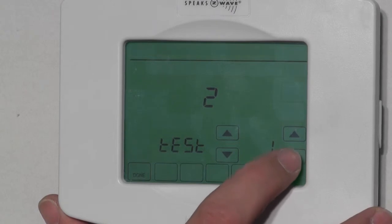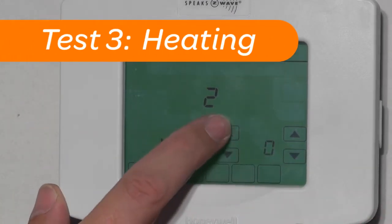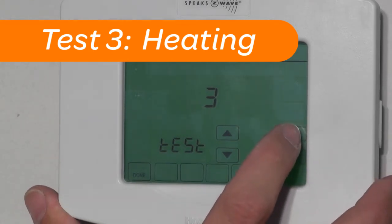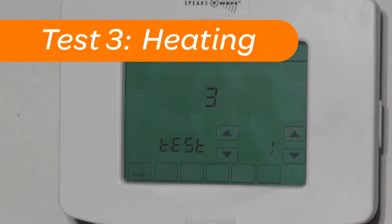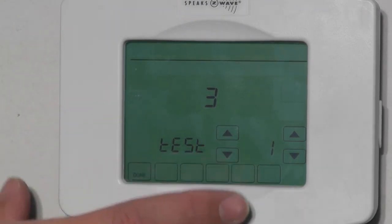with the next test. Test 3 is for heating. On the right-hand side, select option 1 to begin the test. Depending on the type of heating you're working with, be it electric, gas, or oil, the heating equipment should engage. Verify warm air is blowing from the supply registers. If you're dealing with multiple stage heating, you will use the right-hand up arrow to scroll to each additional stage. After verifying functionality, turn the option on the right-hand side back to 0 and proceed.